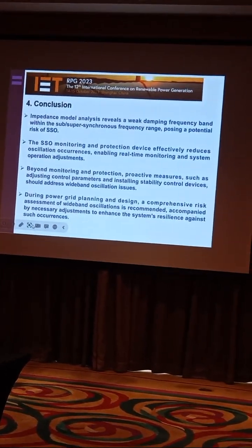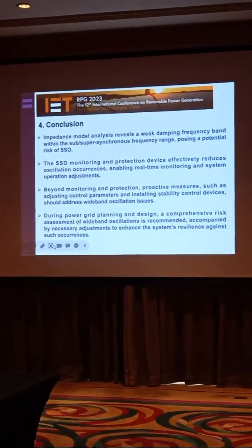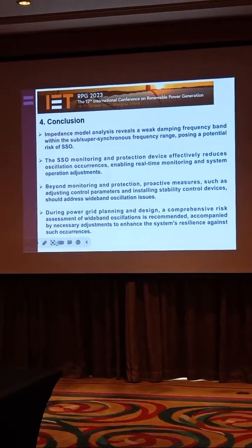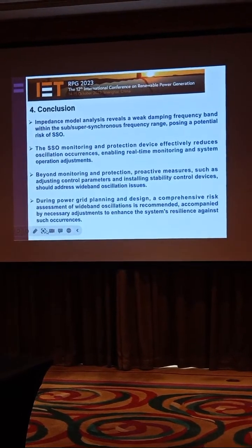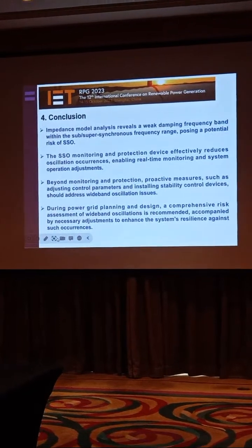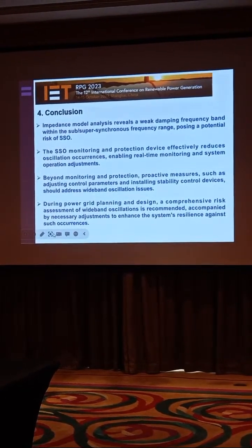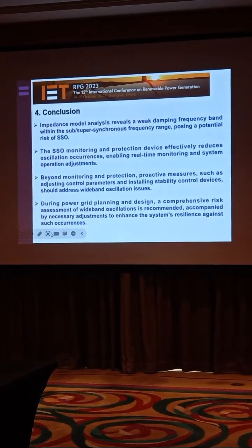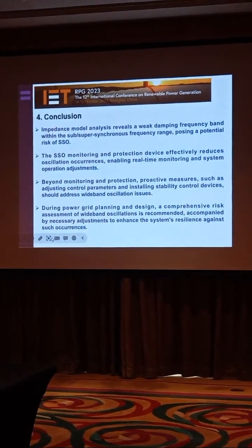Here is a conclusion. Impedance model analysis reveals a weak damping frequency band within the sub or super synchronous frequency range, posing a risk of SSO. The SSO monitoring and protection device effectively reduces oscillation occurrences, enabling real-time monitoring and system operation adjustments.